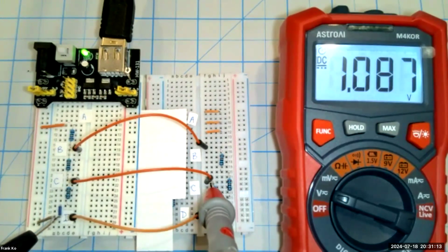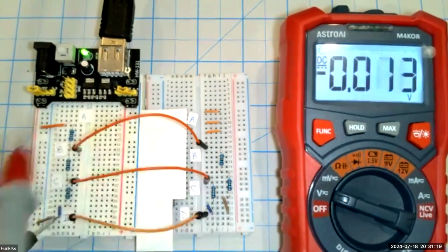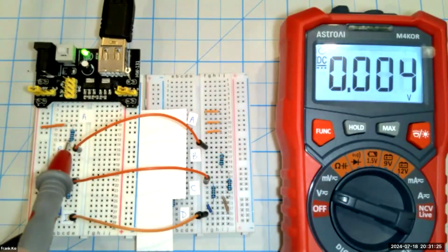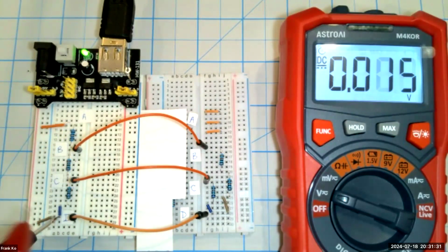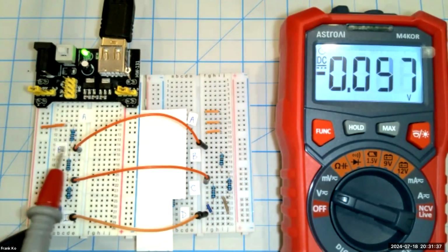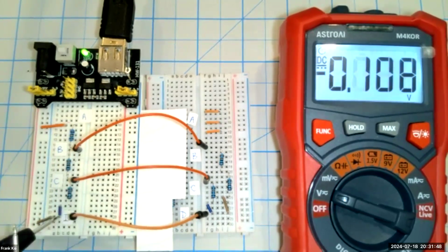So as we surmised in the slides ahead and our calculations, we knew there was going to be a problem. We couldn't keep the original voltage divider values, original 4 volts and 2 volts here, based on those resistor values, the moment we hooked up our loads. So what we needed to do was to calculate new currents going through R2 and R1, calculate new resistances for R2 and R1, and once we put in the correct value resistances, then we would be able to achieve the voltages and the currents that we hope for.